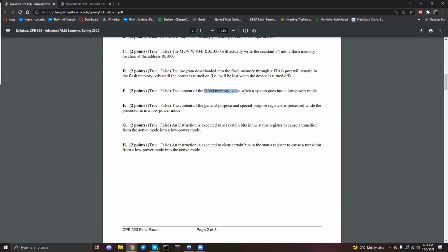It just disables CPU clocks. It just turns off clocks, and doesn't even turn them all off, unless you're in the deepest possible low power mode. But even so, it would make zero sense for low power mode to turn off your RAM, because that's where all your variables are held. Assuming you write programs that use variables like a normal person, if you turn off your RAM, you can't really do anything, can you? Until you turn it back on, you're kind of just frozen.